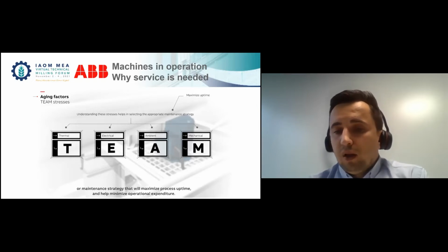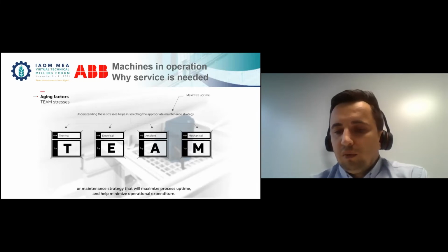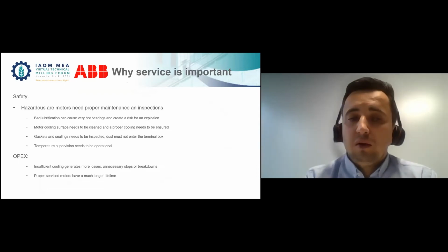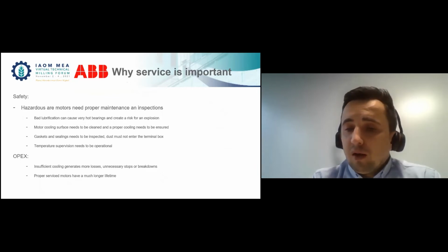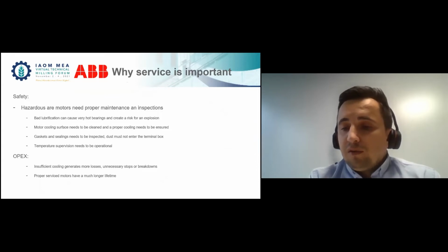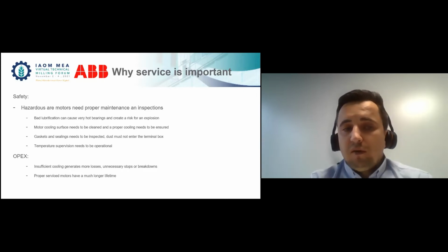And we can support you with different applications, on how to do it in the right way. And there are also some safety aspects. What I saw over the years as well: you install a motor which is hazardous area proof, and then you haven't selected the right bearing for a belt driven application, for example ball bearings instead of roller bearings.